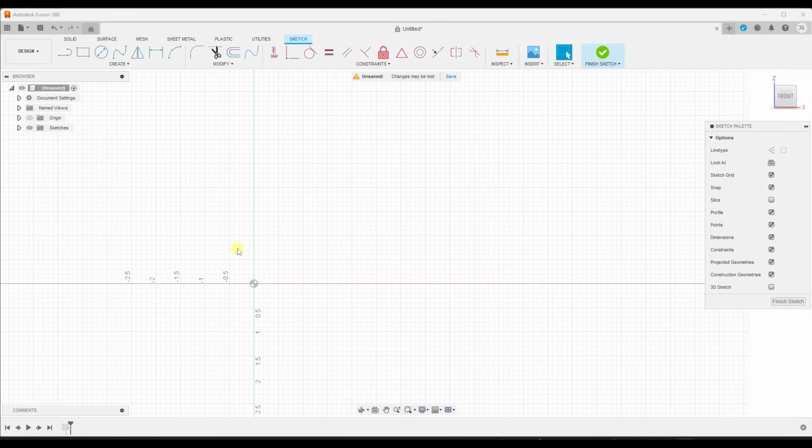So what I'm going to do is mouse over this workspace and tap L on my keyboard. Notice how that highlights this right here, and it also activates that tool in your workspace on your screen. Now, what I can do is come in here, mouse over a point like this, and single click in order to set a point. And so when I do that, notice how this is starting to draw a line in my 3D space.